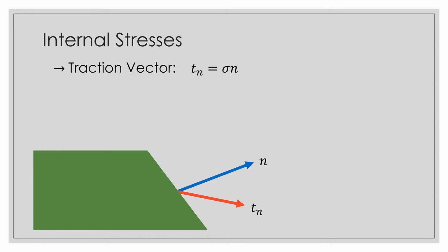But what else can we actually achieve using this traction vector? Well, the first thing is the normal stress. So this is the stress that goes in the direction of n. So if I were to cut this face, then the stress pointing perpendicular to this plane, well, that'll be our normal stress sigma n. And if we look at sigma n, it's a very simple formula. All we do is we take our traction vector and we dot it. So that right there, that's a dot product. That is not multiplication. And we dot it with our normal vector n. So again, the formula is very simple.